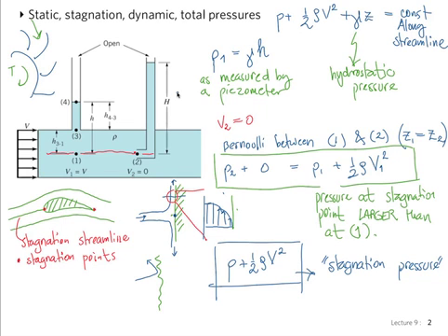Yes? Is it like a sudden stop or a gradual stop? Gradual stop from V1 all the way to 0. V1 is sort of unperturbed in the pipe, and V1 is the same everywhere. If I'm standing a little bit around here, the fluid is going around this obstacle, and so V just around this perturbed area will be adjusting to the obstacle.